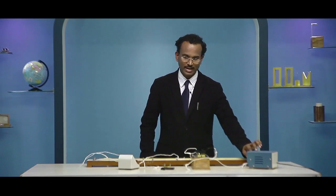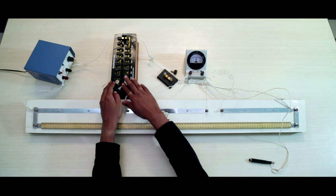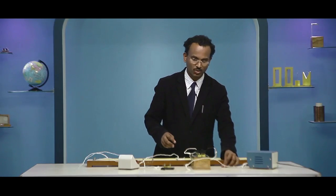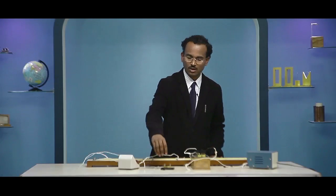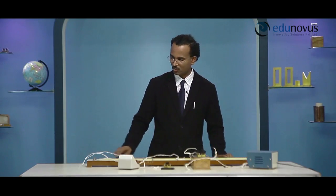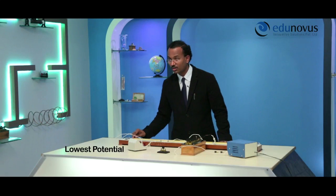Let's check our circuit first. Before I switch on the battery eliminator, I should include some resistance in the resistance box. So let me include 7 ohm resistance. I do that by pulling out the plug from 5 and 2 in the resistance box. Next, I will switch it on. Now to close the circuit, I will plug in the key. So now current is flowing through the meter bridge wire. This end will be highest potential and this end will be the lowest potential.